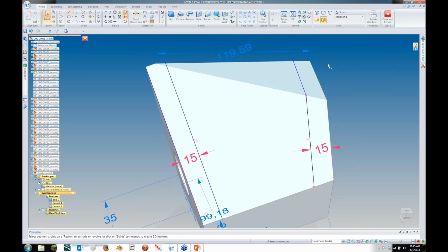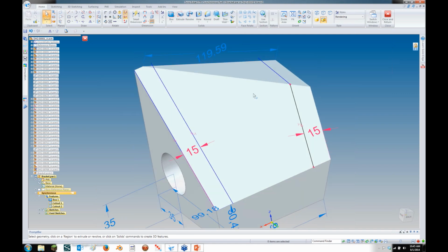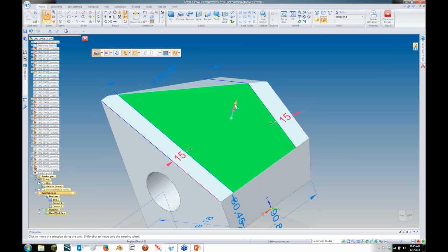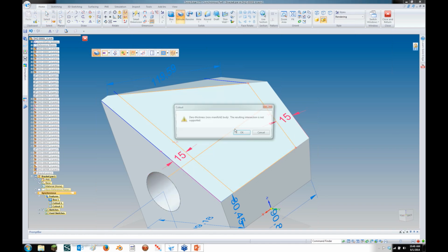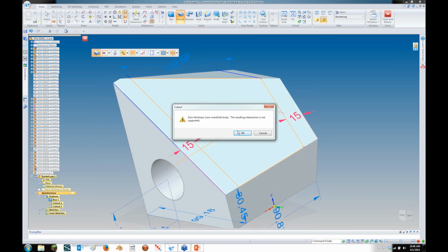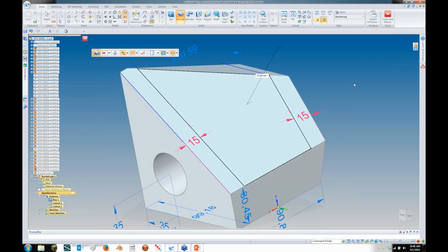That will work. All right, so let's knock some of this geometry out here. Now I have a closed region. I'm going to drop this face a little thicker than I'm going to actually make the part. So I'm going to go down 2 millimeters. Oops. I think I just typed in too much of the distance. Here, let me grab this first.